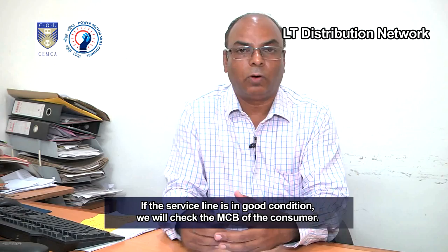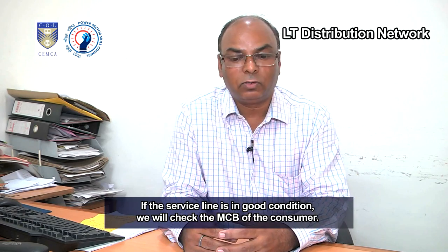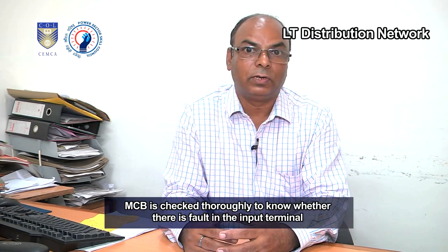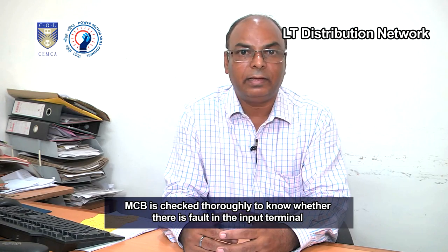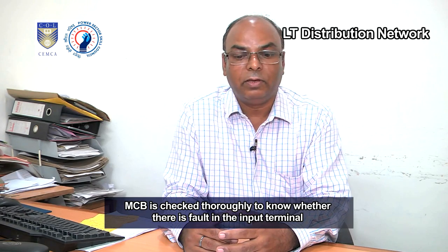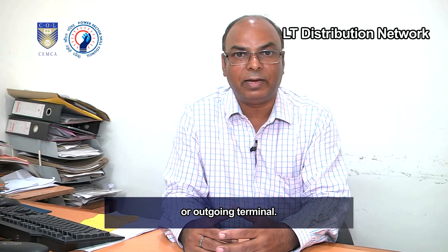If the service line is in good condition, we will check the MCB of the consumer. The MCB is checked thoroughly to know whether there is a fault in the input terminal or outgoing terminal.